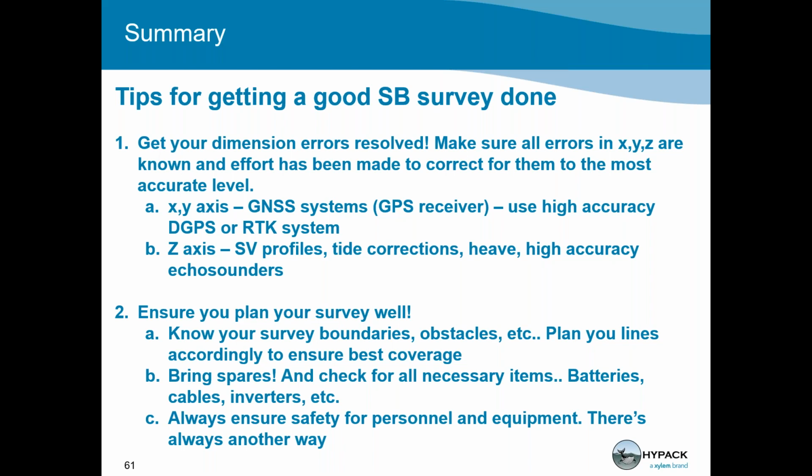Okay, there's a question here about any recommended boat speed for an accurate survey. What are your thoughts on that one, Boris? Or even Phillip? I think it depends on the resolution that you want. I mean, the echo sounder that you have can only ping with a certain frequency. So let's say it pings with 10 hertz, depending on the depth, of course.